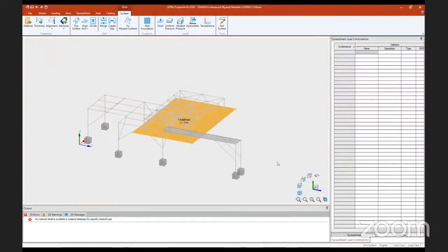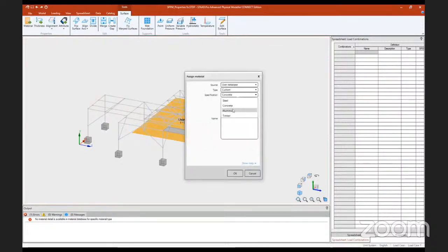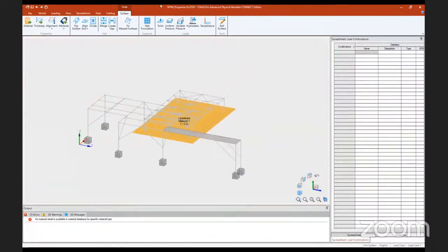That's a nuisance. So if I come in here, let's just save that. And let's do that one again. So if I go for material, so select concrete, let's see, catalog, steel. So I'll just go for that, click on here. And the thickness, I want to put in as say 450, so 0.45 of a meter, and assign that in here.